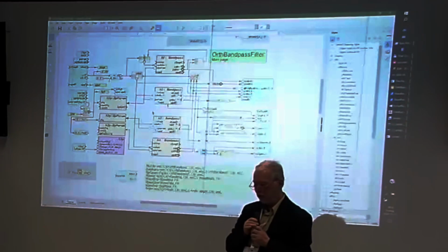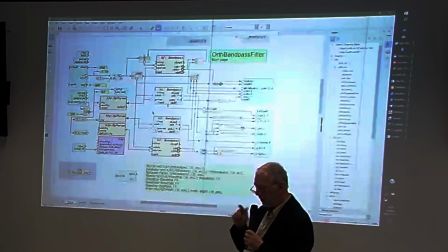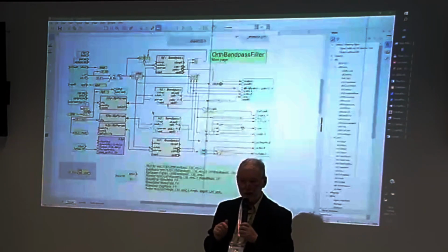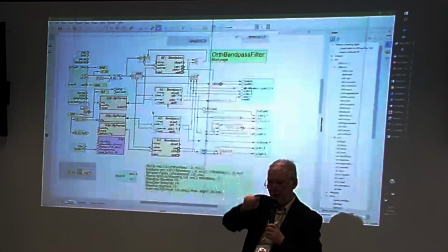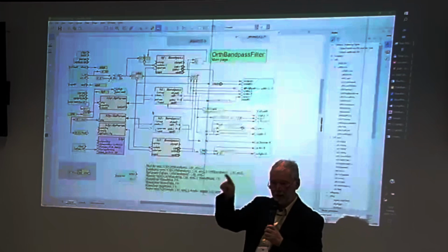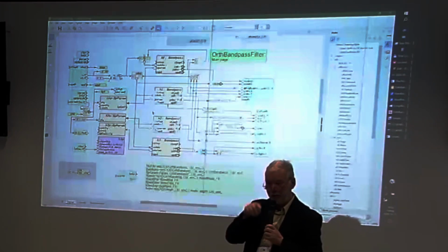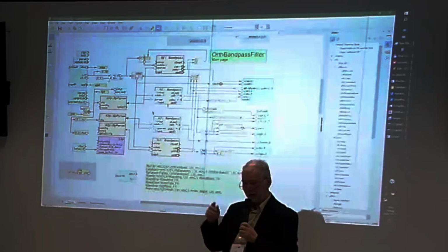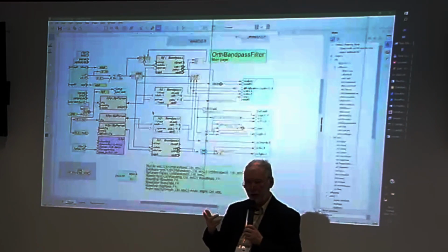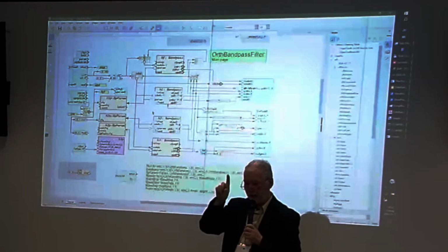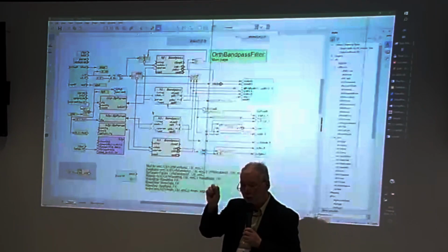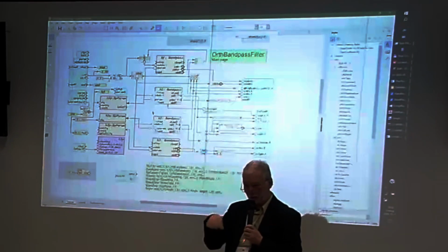This is the other solution. Simulink uses the data flow. The data flow has the problem that if you have a flow around loops, that is an error, and you need a unit delay in this loop, then all works.